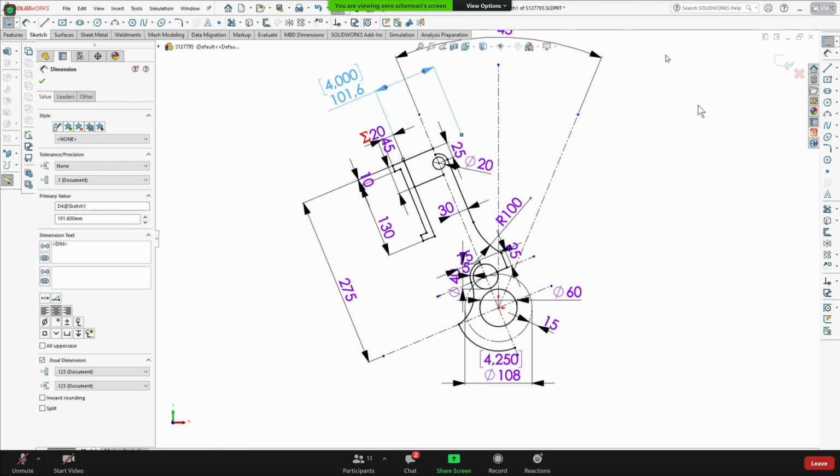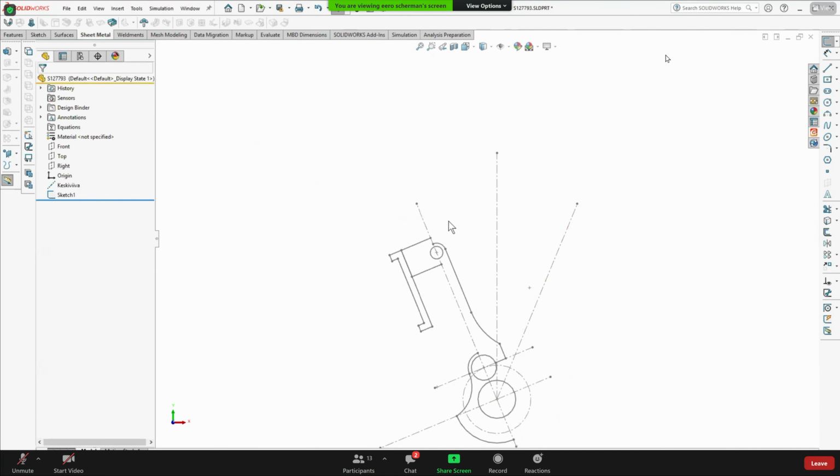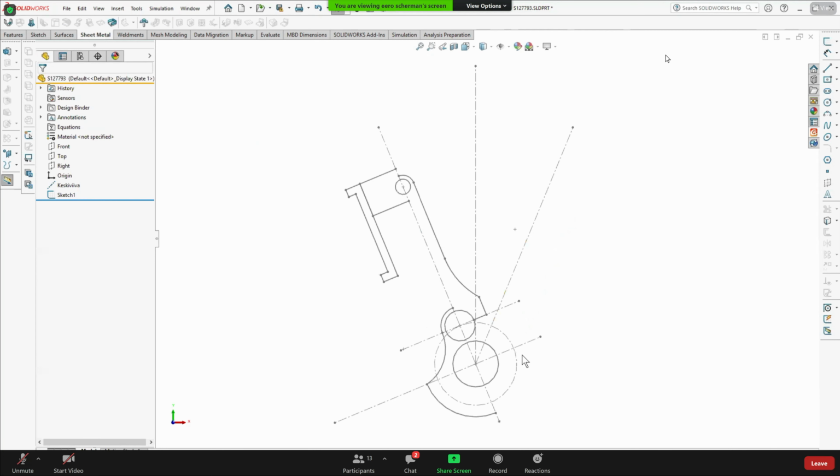Anyway, the first thing is to create the sketch. And I would say that making this sketch is the hardest part in this kind of modeling, because you have to think everything through, how to make this sketch work. After the sketch is finished, you do not create any parts in this single part. Instead, this part, including only the sketch, is inserted into a new part.